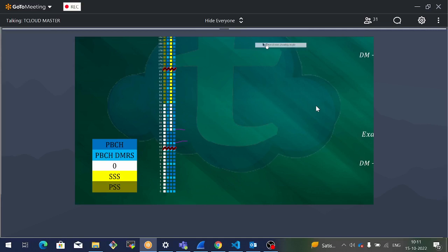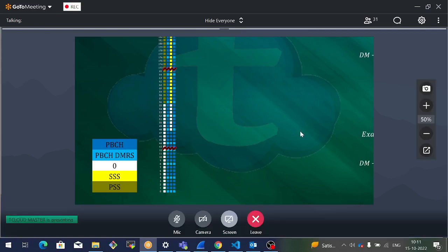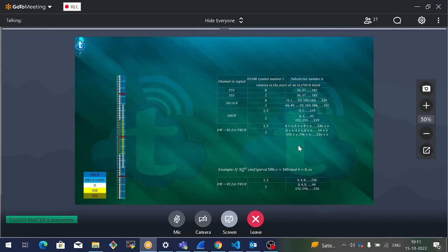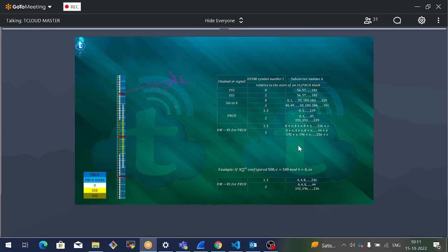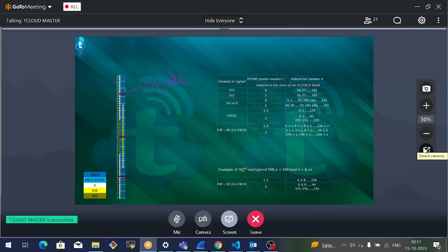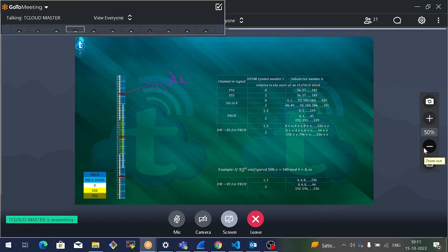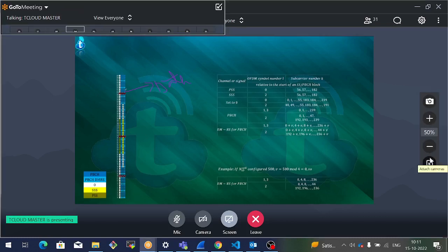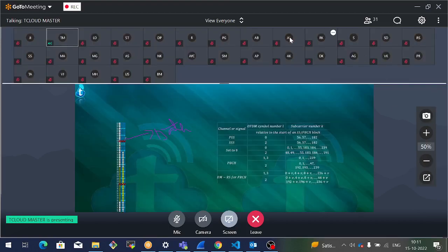Okay. Now, one thing is very clear. This PBCH channel, which is present in the dark blue color, contains some data for sure. But in order to decode the data, you definitely need to know its position, the PBCH positions in this particular SSB block. If you cannot find out the position, you cannot decode it because everything goes wrong. All the information you think is the data is not your data.